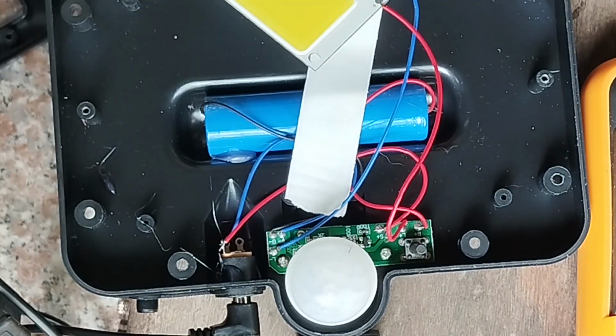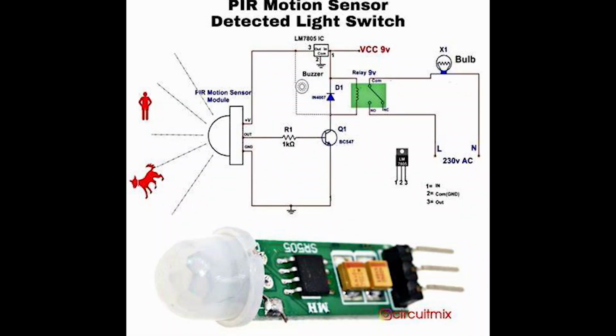Under the topic of passive infrared sensors, also known as PIR sensors, we have a single passive infrared sensor standalone or the module. In most open markets like eBay and AliExpress, you can find passive infrared sensor modules. As a module, you can directly connect it to your circuit and start switching using a normal NPN transistor.